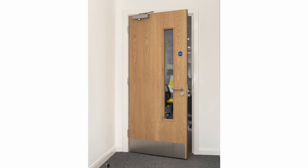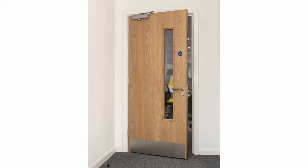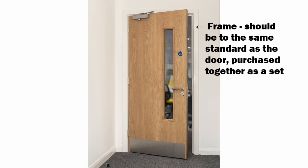Fire doors. Buildings are compartmentalised to delay the spread of fire from one area to another. These compartments are usually linked by fire doors to allow the flow of traffic around the building. Fire doors have two important functions in a fire. When closed, they form a barrier to stop the spread of fire, and when open, they provide a means of escape. A well-designed timber fire door will delay the spread of fire and smoke without causing too much hindrance to the movement of people and goods.